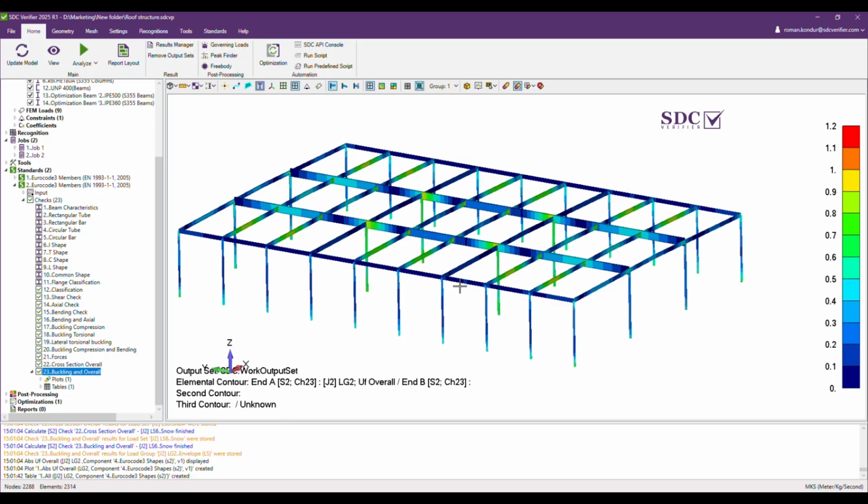We can apply the loads, we can predefine the constraints, we can execute static calculation with the Nastran solver and check the stress level in the structure. But in order to be sure that our results are well within the allowable limit, for the roofing structure, we need to additionally calculate the beam member check according to the Eurocode 3 standard, and that's everything possible in one place.